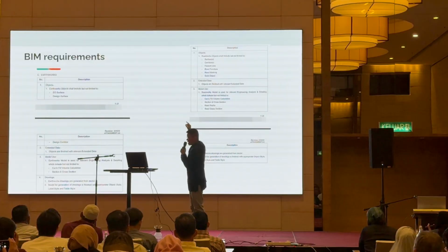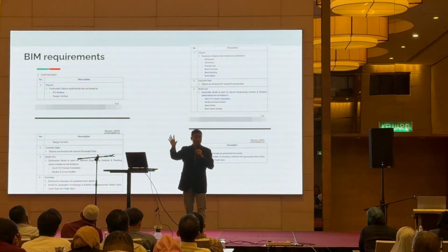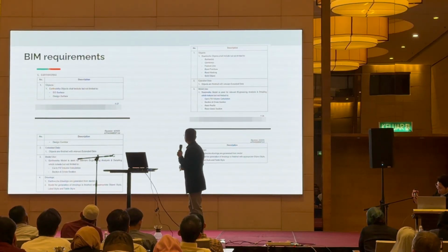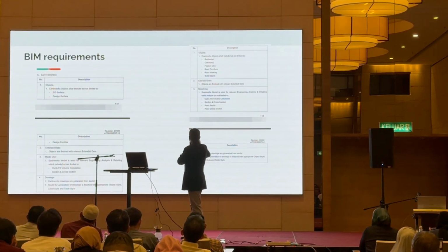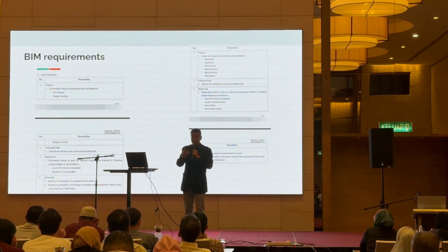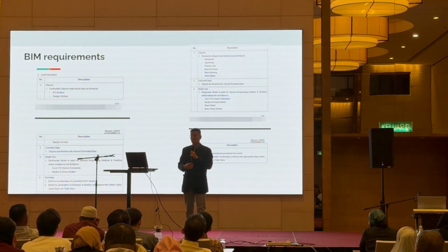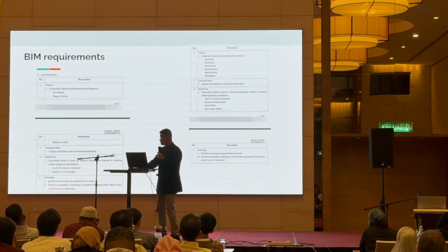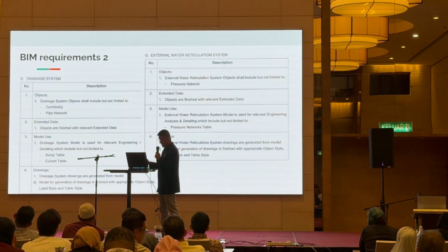Then, of course, surface and corridor are all Civil 3D things, like what you have seen. Corridor is just 3D road profile. Then you have this road furniture, road markings. These are not Civil 3D objects, but we're going to put them in also. And also the view volume, section and cross section. These are all like what you saw just now, like the profiles, sample lines, groups, and all those things, the one we also demoed by Patricia. So here are the recaps of the pipe networks.